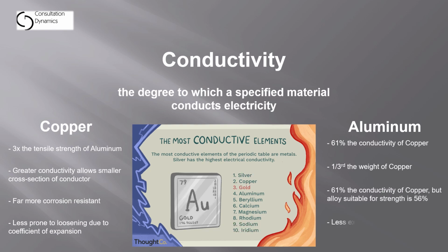Now, normally, the aluminum that we work with, particularly in lighting fixtures, is not raw aluminum. Raw aluminum is too soft, it galls too easily, or when you go to machine it, it breaks; it doesn't just sand or machine smoothly. And so there are always additives to it, which is what creates aluminum alloys. Now, alloys of aluminum, which include mixtures with silicon or magnesium or zinc, cause aluminum to be less conductive.